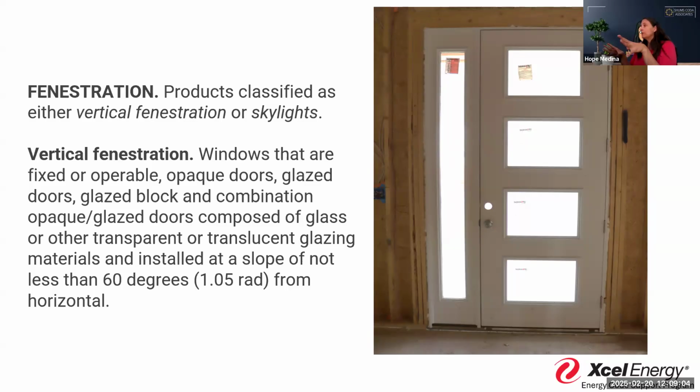So my question for you all, raise your hands, because you've sat there now. How many of you call this door an opaque door because it's more than 50% opaque? Okay, raise your hand if you say that it is a fenestration. All right, good job, Robert. You're right. This door is more than 50% glass. So because it's more than 50% glass, we would pay attention to the requirements of the fenestration rather than the requirements of the opaque door.